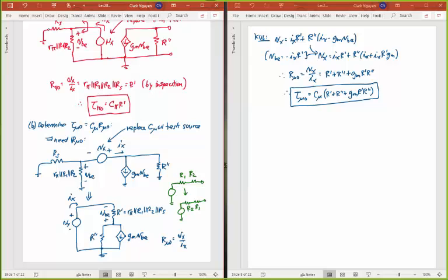That's pretty much what I did right here. I said, this is one of my elements, this is another of my elements, and I just juxtapose them. I move that to there and move that to there, because they're both in series to ground from that point. And so I just juxtapose those two. I had to be careful to change the polarity of the plus and minus of VBE so that it stayed the same as the polarity here, right? But that's how I was able to push R prime on this side of Vx.